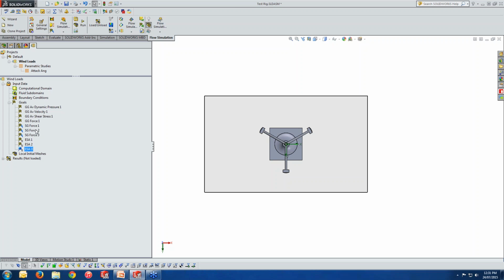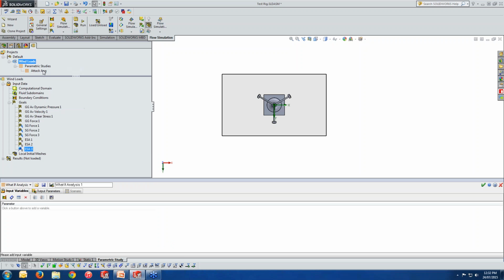However, this said, we are going to have different angles on this case study. Well, the whole antenna unit and structure is simply rotating from its position at 0 degrees, that one, up to 90 degrees. So what we need to do is very simple. You go into your project, right click and say, I would like to run a new parametric study.